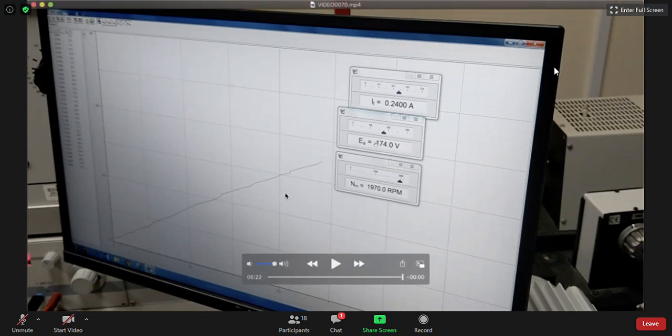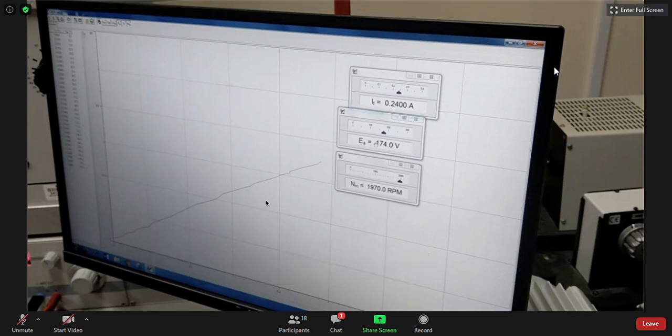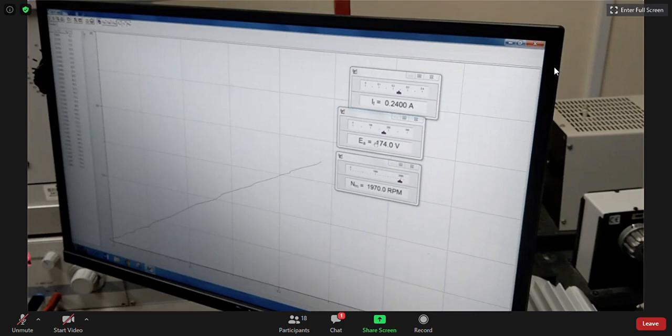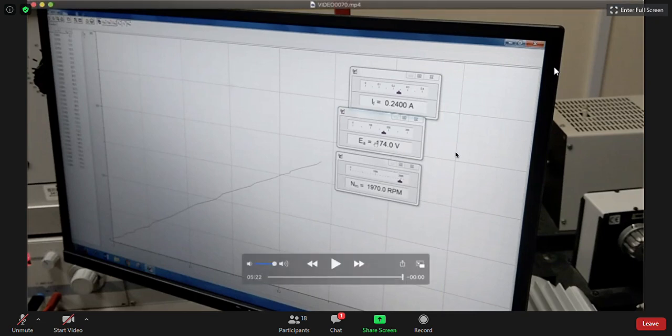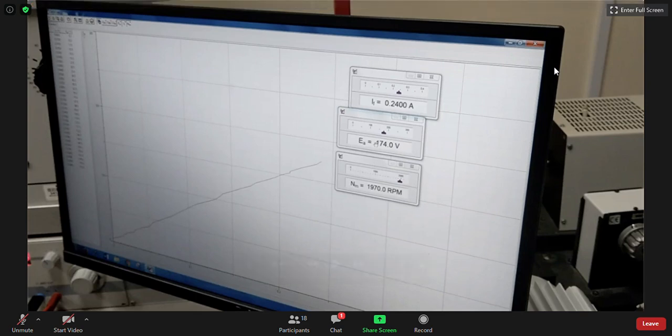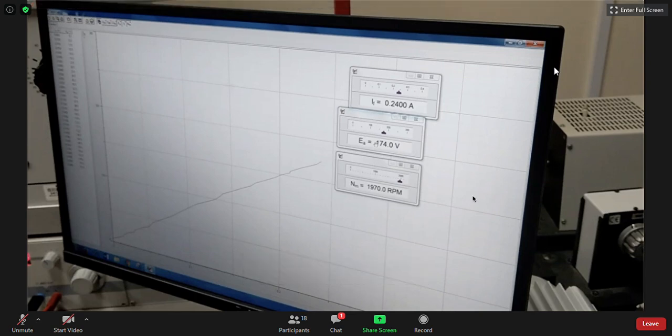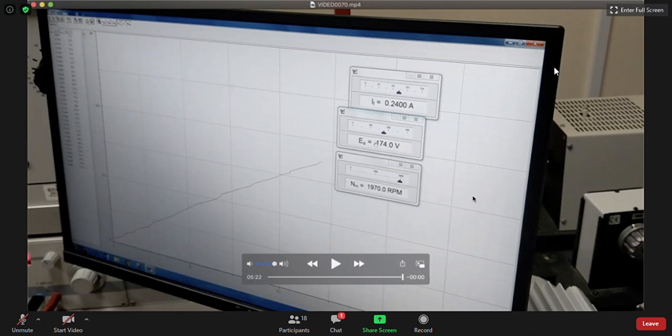IF versus EA, which is the generation of the generator. But it can saturate at the end because this is the magnetization characteristic. It can saturate if you increase further because the machine has some limitation. But in general, our relation between flux and the production of E, which is voltage, is directly proportional, which is verified in this experiment.